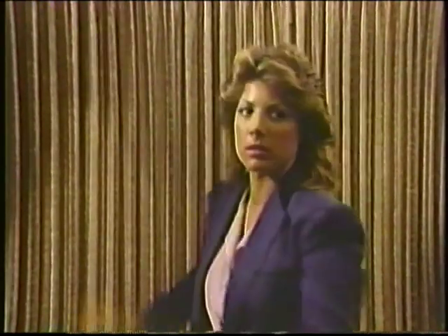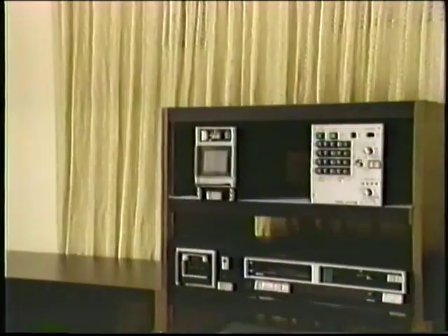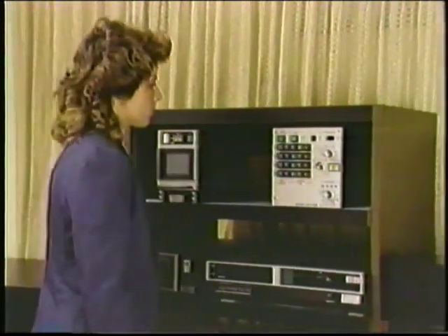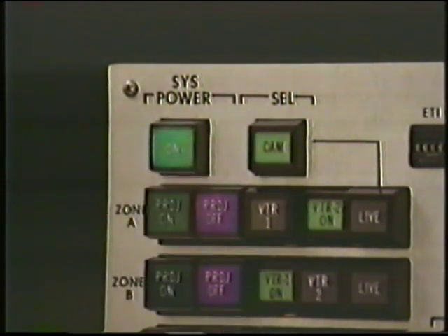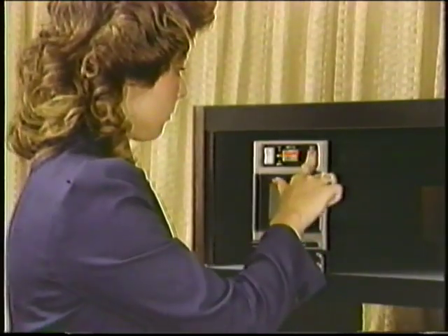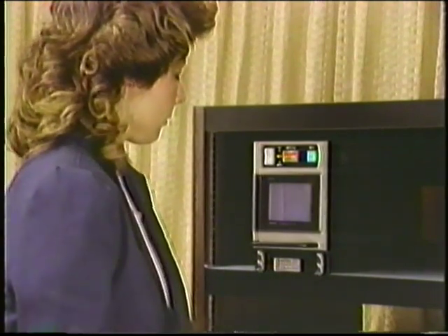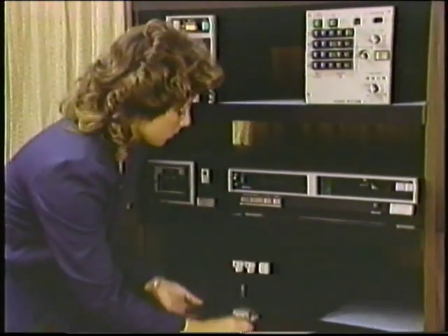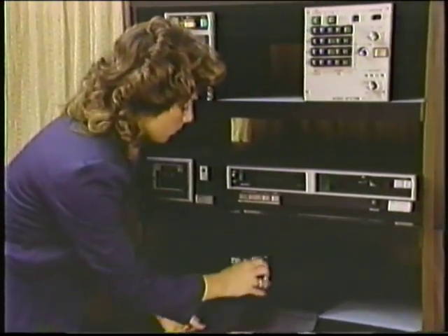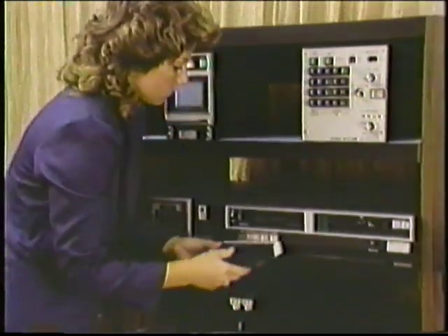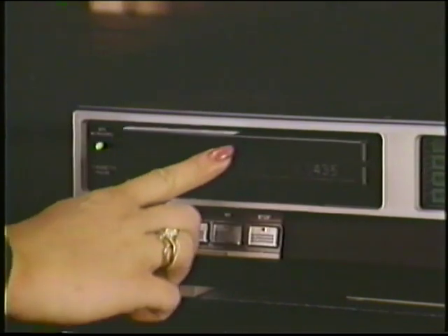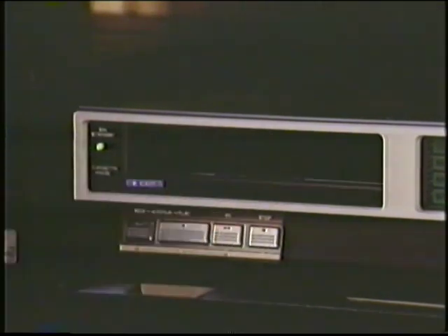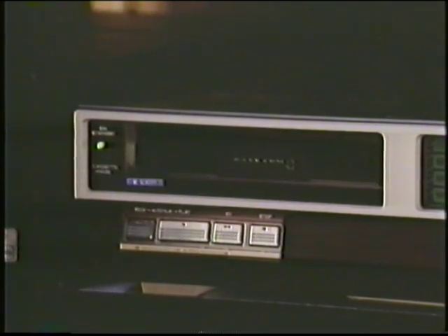Let's briefly review the operating procedures of the Transcom video system. Start the system by turning the power on at the SCU. Turn on the 4-inch monitor. Verify that the VTRs are on. Position the cassette properly and place it in the VTR. Remember, the quad VTR will load itself automatically. Don't force the cassette in.